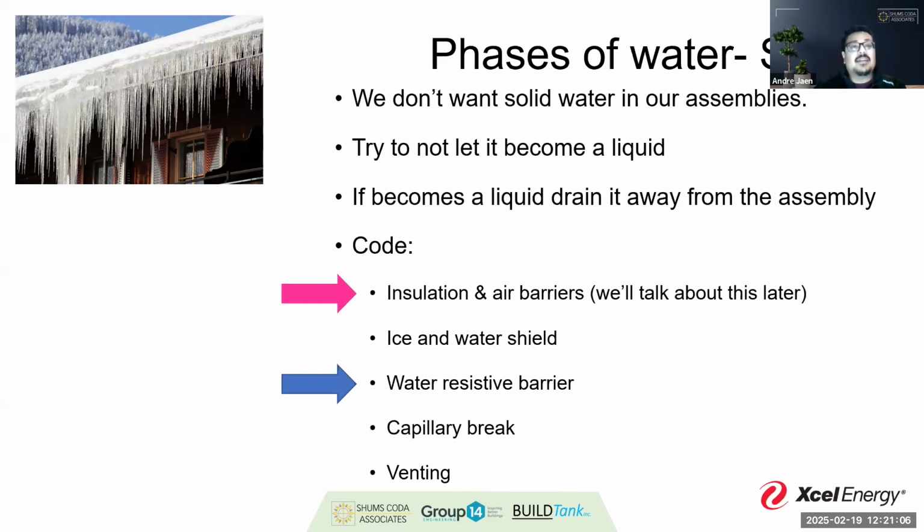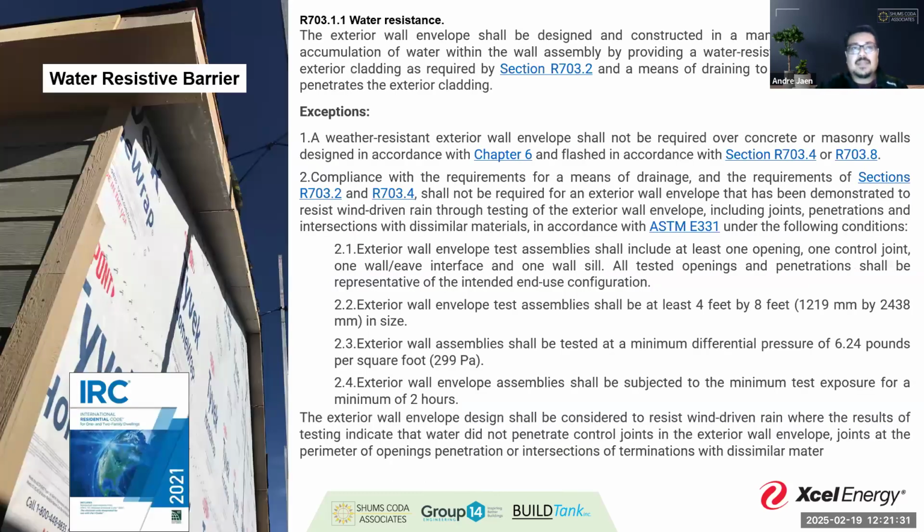But that being said, that's really recognizing the fact that we have a high propensity for intrusion in this particular place. The framing there is difficult to maintain, getting a consistent, tight seal, and that's where water wants to accumulate because of the freeze-thaw process, and it loves to just worm its way in there through the capillary effect and really start to work up some of that roofing material.